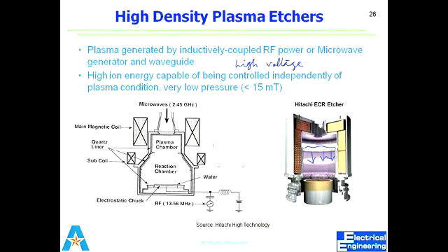So the passivation layer on the side, in the etching cycle, that sidewall passivation layer is removed, but I have moved deeper. Again the passivation cycle comes, so the sidewalls have a passivation layer, that is removed, but at the same time you move deeper. So this way you keep on moving deeper and deeper, but you don't move sidewards. It's only in the first cycle that you move, and in that case you move deeper without moving in the lateral direction.